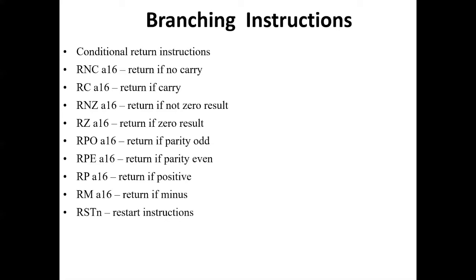RNC A16. RNC is a mnemonic which stands for return if not carry. This instruction is used to return to the main program only if carry flag value is 0. If carry flag value is 1, program flow continues in the subroutine sequentially. It is a 1-byte instruction.